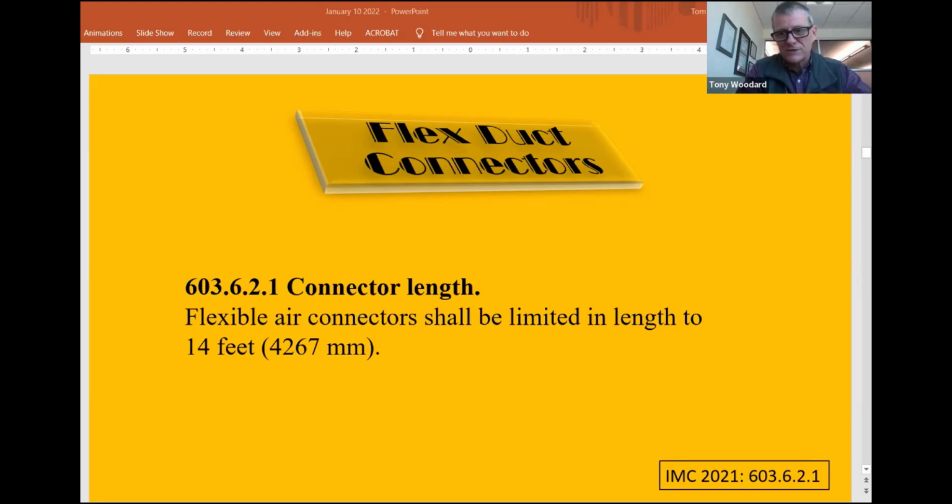Take a hospital setting. Each has its own individual private room, and each room is controlled by its thermostat. When you turn that, you open up the damper, which allows the duct to open up, go into the VAV box, and treat the room. All you're doing is that trunk line that's running is feeding that individual room.